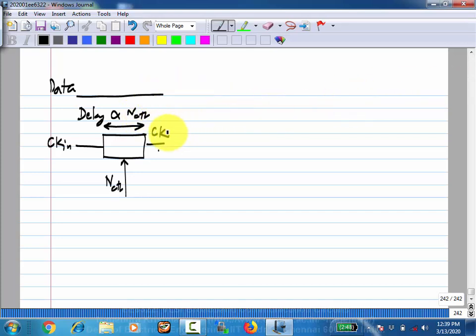So what it means is, how we implement it we'll come to later, but most often one of the possible implementations is you can make a delay line and then switch the delay lines in and out, or you have a circuit which generates a whole bunch of phases, right? And then you select one of them. It's all the same thing. It will make a difference for implementation, but they work in the same way. Essentially, based on a digital input, you pick one of these phases.